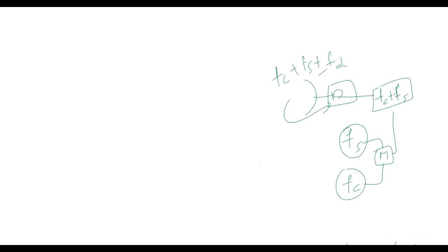Next, what is explained in the explanation part? What is the full form of STALO? Stable local oscillator, which is represented with FS. Next, the coherent oscillator, which is represented with FC. We are combining these two in the mixer. After combining in the mixer, what will we get? FS plus FC. Where in the diagram is this FS plus FC fed? We are applying it to the Doppler effect. After that, we will get FS plus FC plus or minus FD.